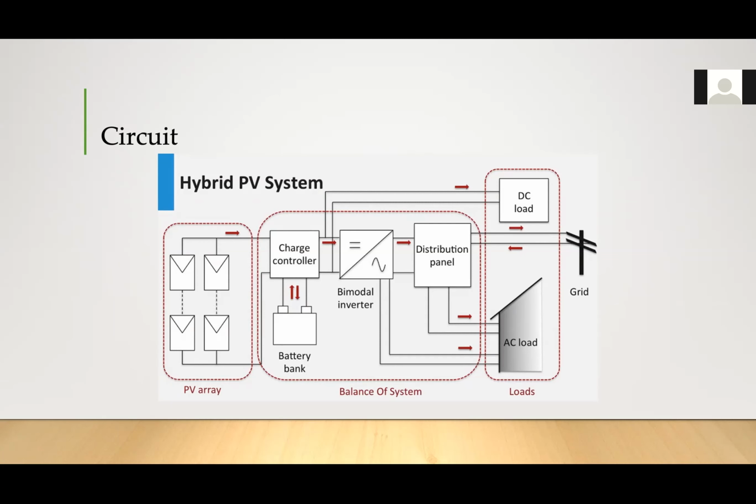Being that they act the same way as voltage sources, putting them in series, you're going to get the summation of them, and the current is going to be the same throughout both. But when they're in parallel, you have the same voltage across each path, but you're going to get a higher total current. And from here, it goes into the charge controller.